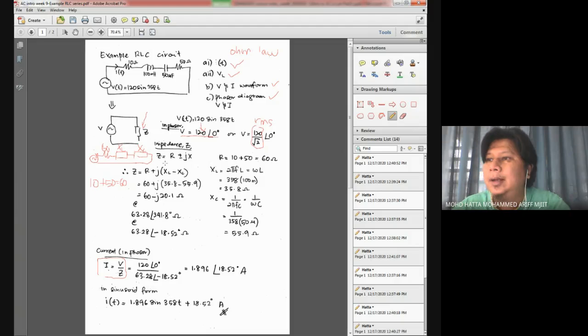All right, impedance. Impedance here is the combination of R, L, then C. So it means that our final value of impedance should be based on this equation, Z equals R plus or minus jX, and we don't know what sign it should be over here until we finish the summation, where we add those two, XL and XC. Before we get into that, we need to find what XL is first.